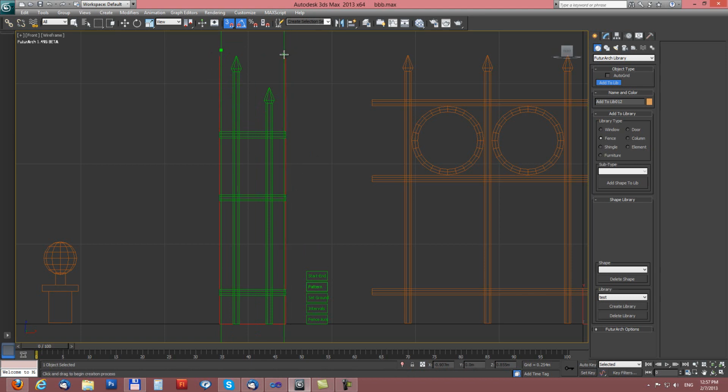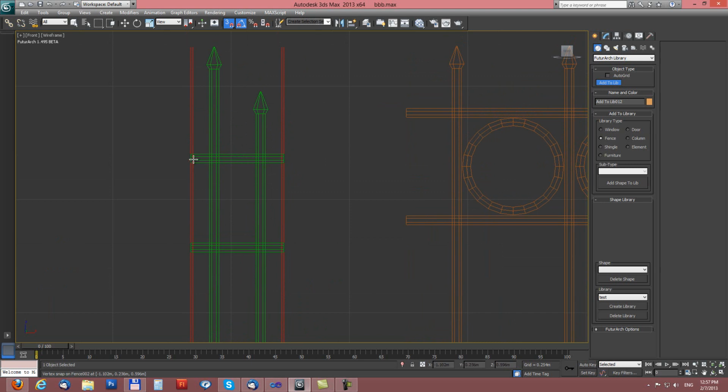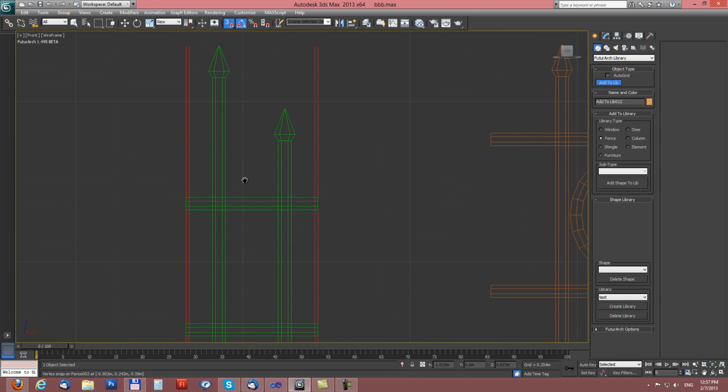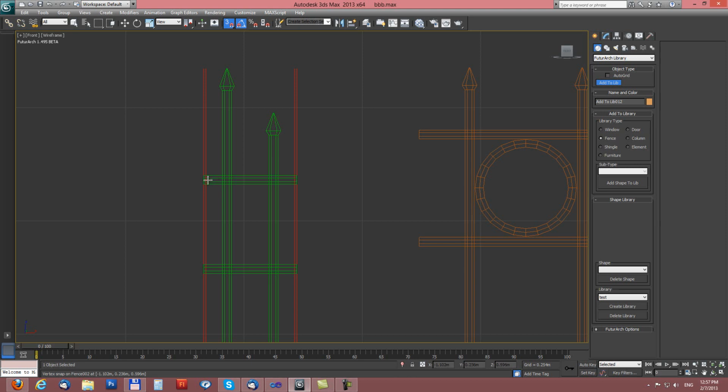I will define this interval a little bit smaller than a start end interval, because if you have this part of this horizontal pipes, if these horizontal pipes are overlapping from the pattern interval, so they are a little bit overlapped into start interval, also into the end interval.